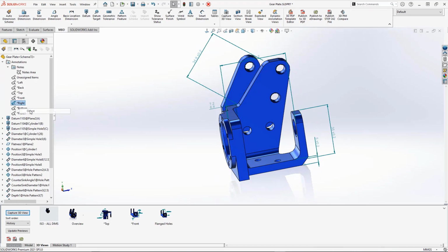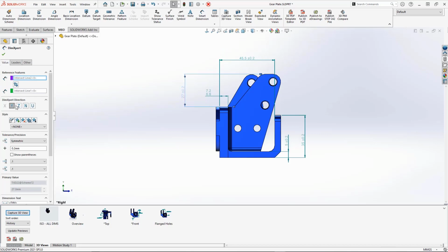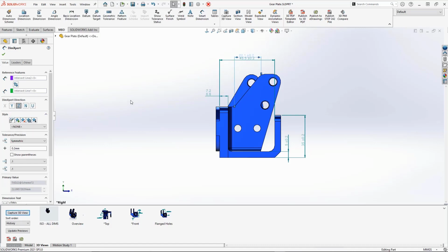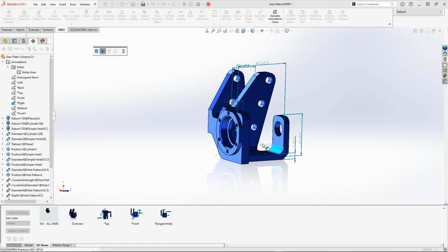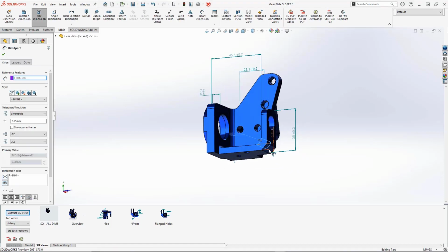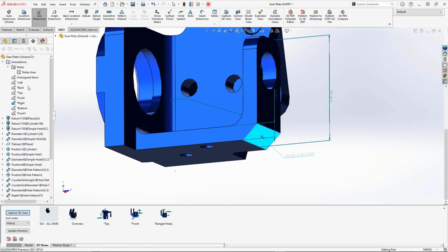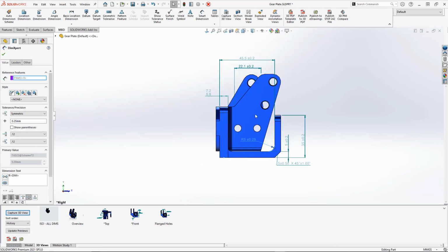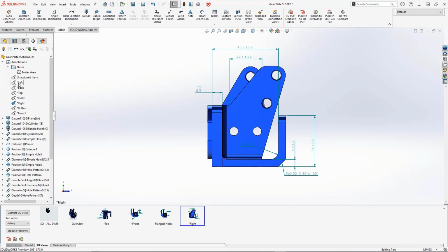Now, I can really at any point in time customize this as well. Just click on the actual dimension, make it relative to Y, Z, normal to the original selection, or I can even choose a user-defined direction. We're going to leave this on Z, but this does provide us with those exact intersection locations on those fillets. Size dimensions are extremely easy to add. Simply click on faces to add fillet sizes or chamfer sizes as well. So we can also manually add information to make sure we call out what is critical inside of our model. Again, once completed, make sure we capture this as a 3D view referencing that specific annotation view.